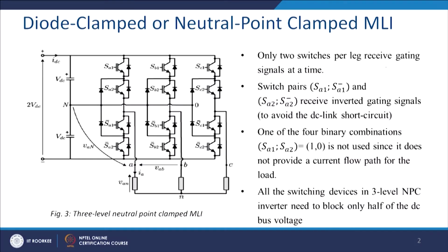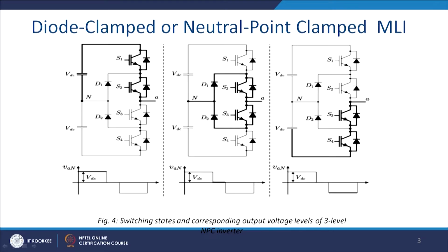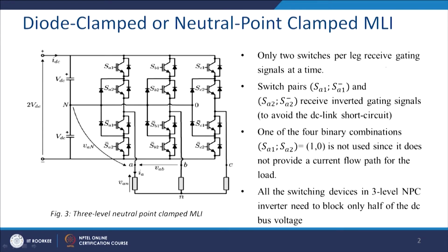Today we will continue with space vector modulation, but applied to the multi-level inverter. We have discussed the 2-level inverter; now let us see how this concept can be extended to the 3-level inverter. We shall revisit the diode-clamped inverter again, but the purpose here is something else. We will be discussing the 3-level inverter and its space vector modulation.